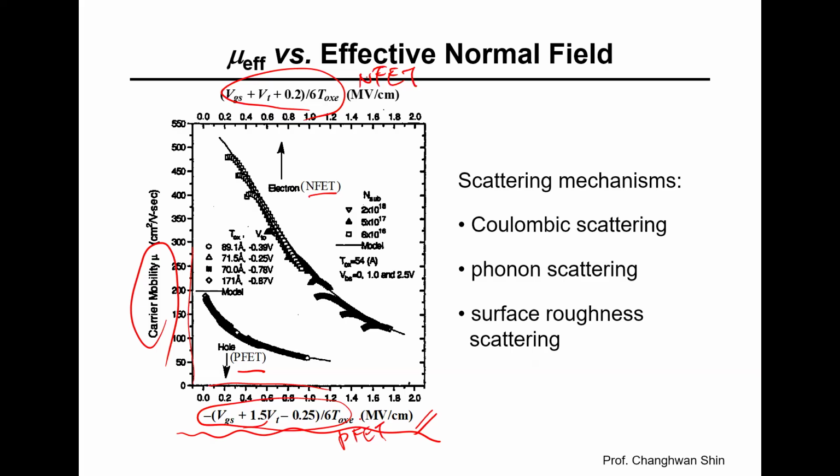All right. Several important trends are evident. First, electron mobility, upper curve, this guy, is significantly higher than hole mobility, lower curve, okay? Maybe about 2 or 3 times greater under comparable conditions. This is why NMOS transistors generally provide more current than similarly sized PMOS transistors, like how sports cars move faster than trucks, even on the same road.